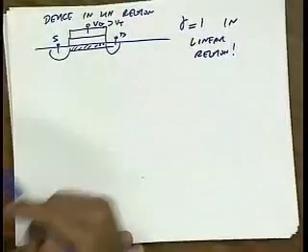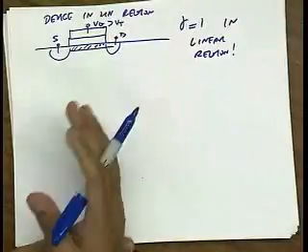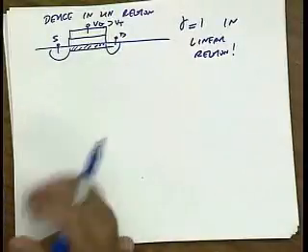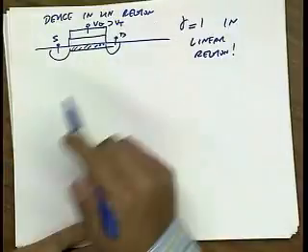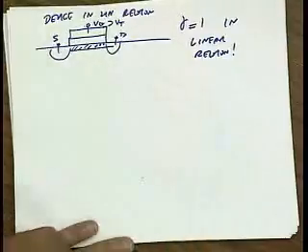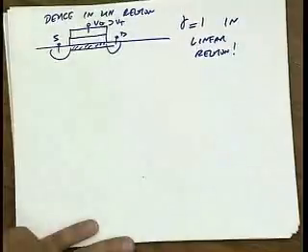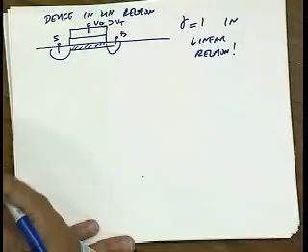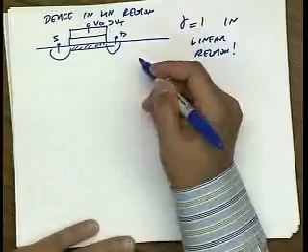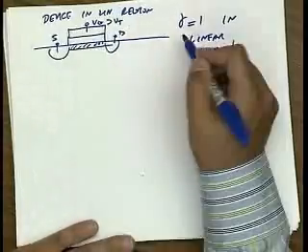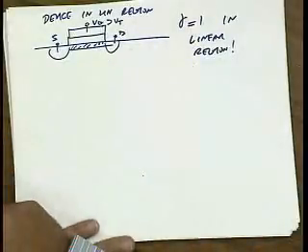Well, part of it is that the thermodynamic equilibrium that we assume occurs in a long channel device is not really happening in a short channel device. In a short channel device, the average temperature of a conductor could be much higher than the device average temperature. That's because in a short channel device, the fields are very large, and carriers are moving at velocities approaching the saturated velocity. So the average temperature is much higher. One way to calculate it would be, when you do that integration, instead of taking T as a constant, take T as the actual temperature at that given point in the channel. And that will show that gamma gets larger.